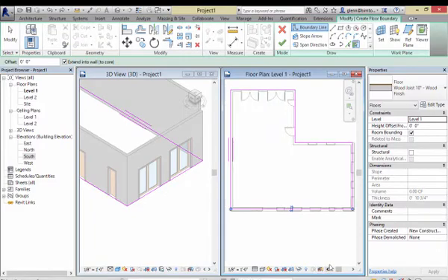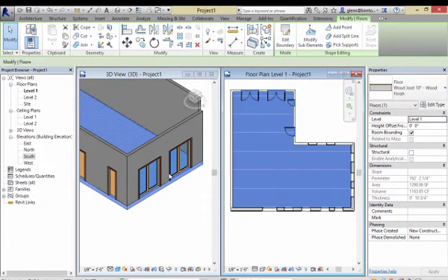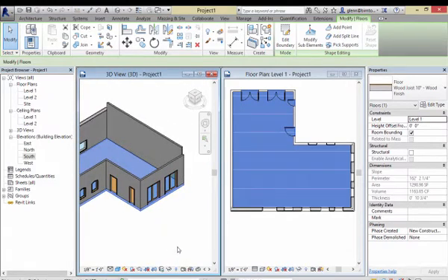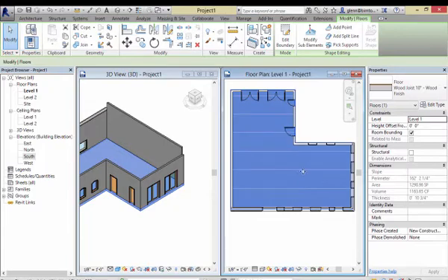And after you've defined the geometry, here's the only thing you have to watch out for with floors. We'll play around with this again a lot next week. Floors have to be cohesive boundaries. They have to be continuous boundaries that go all the way around. It has to be a loop that joins. If yours isn't a loop, it won't join. It won't know how to create things. It has to really fill the loop. And we'll complete it by clicking the green check mark to finish that. And we'll put a floor in there.